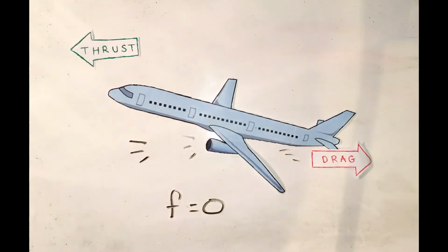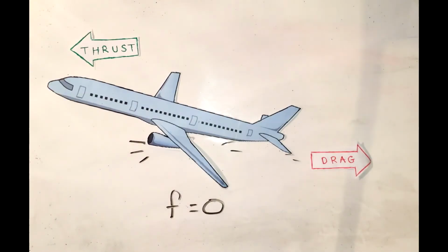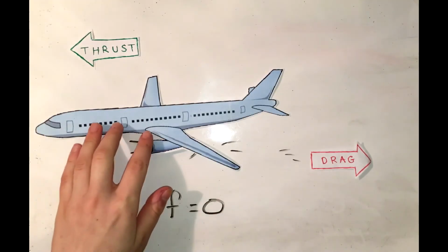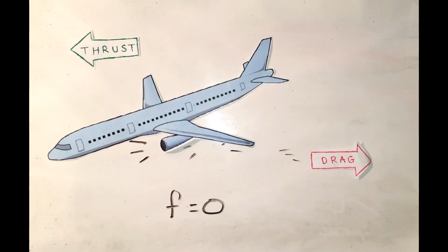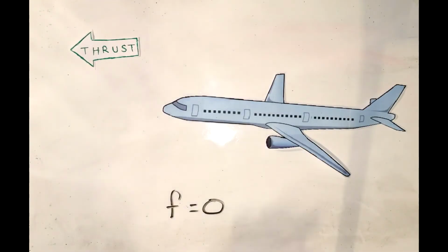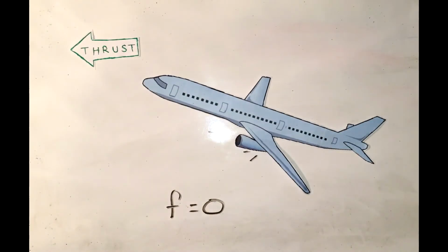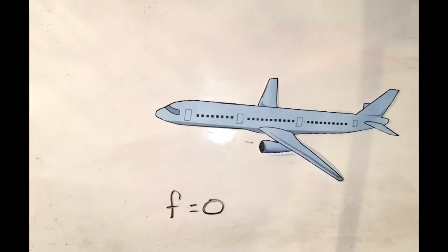The pilot coordinates the angle of attack and thrust to maintain level flight. As the airspeed varies due to thrust, the angle of attack must also vary to maintain level flight. Where the airspeed is high, the angle of attack must decrease to maintain level flight. Similarly, where airspeed is low, the angle of attack must increase. Pilots must take care at low thrust settings and low airspeeds so as not to exceed the critical angle of attack. Failure to do so will result in stall.